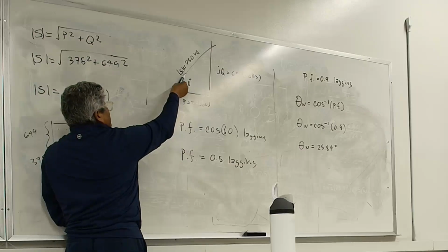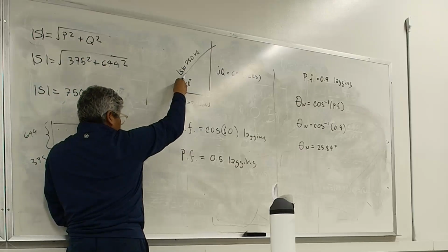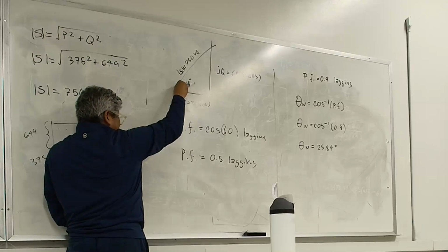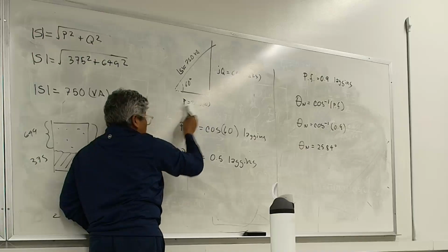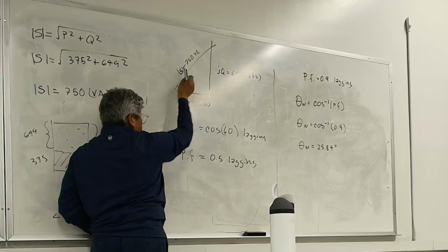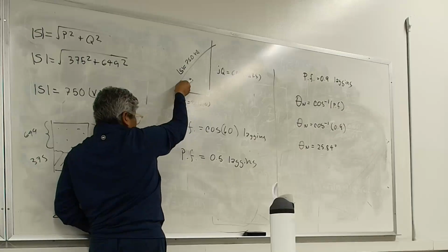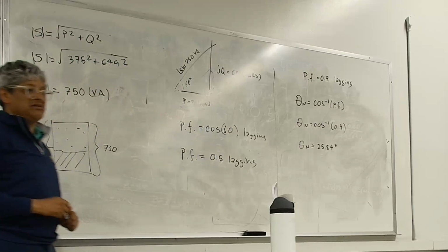Basically, what this is telling us is this. Here's 60 degrees, and they're asking me to include the power factor of 0.9, and if I go through that exercise, all I'm doing is reducing the angle. Reducing the angle results in reducing this magnitude, right? Not this, I'm not touching the real power. What I've been asked is to bring this down. If I decrease the angle, of course, I'm bringing the reactive power down.